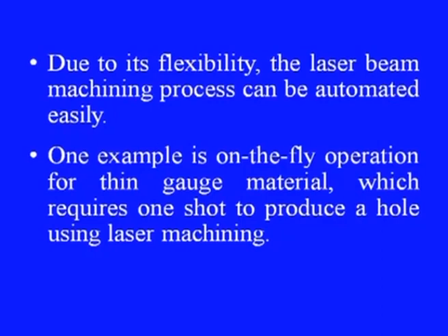Holes can be drilled at different entrance angles, for example 10° to the surface. Due to its flexibility, the laser beam machining process can be automated easily. One example is on the fly operation for thin gauge materials, which requires one shot to produce a hole using laser machining.